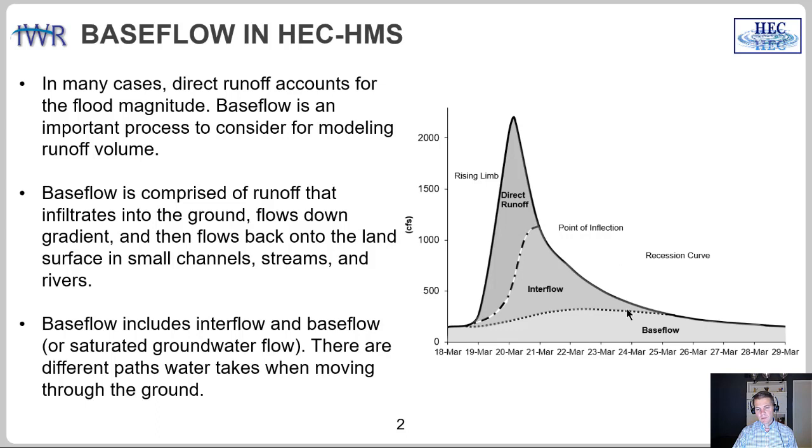The base flow component, so interflow and base flow, those are important too. They do contribute somewhat to the peak flow, but they're mostly going to contribute to the total runoff volume. So if you're looking at problems that consider volume, so maybe sizing some kind of detention structure, or you're looking at duration of flow above some threshold, then that volume or that base flow is an important consideration.